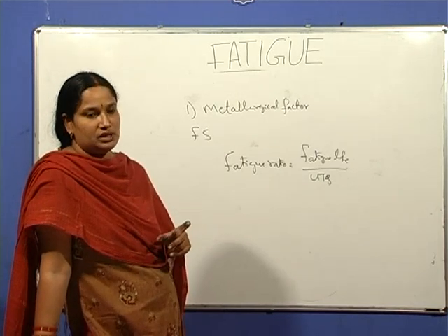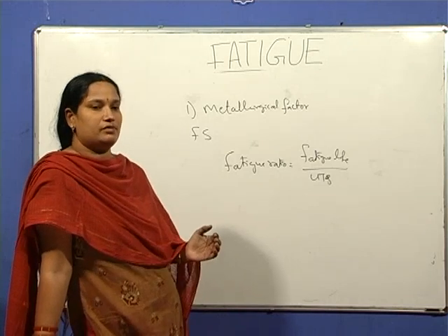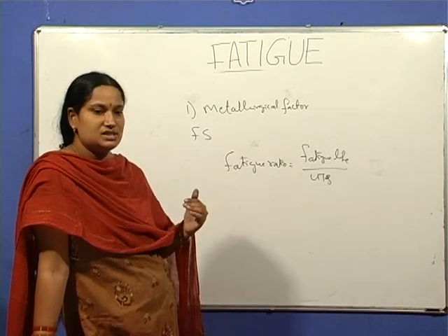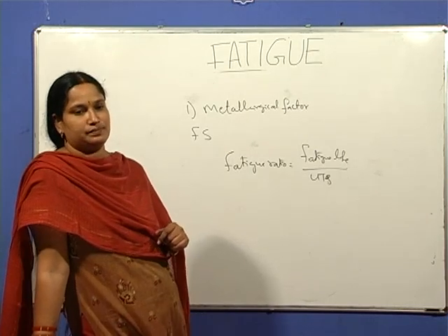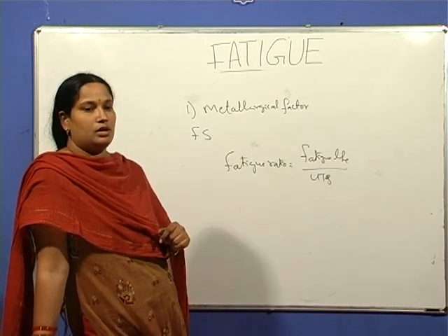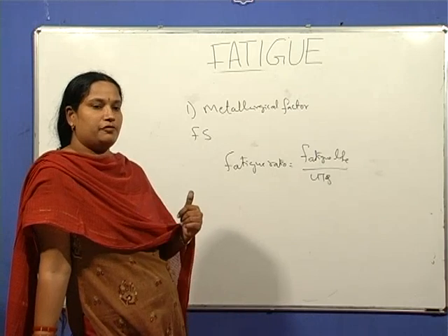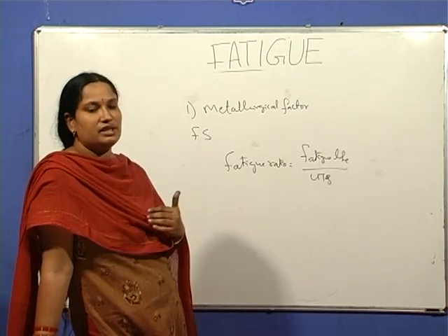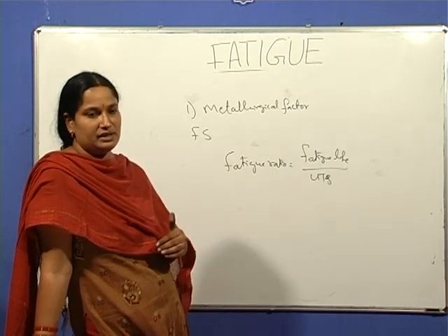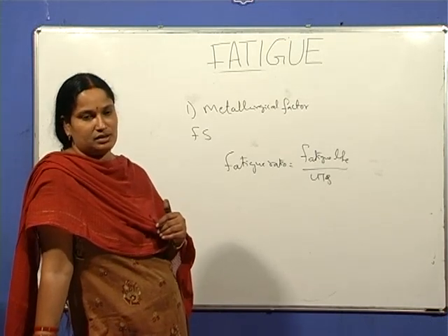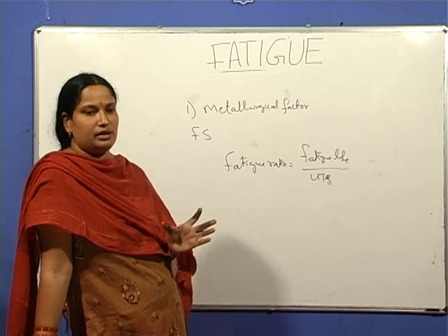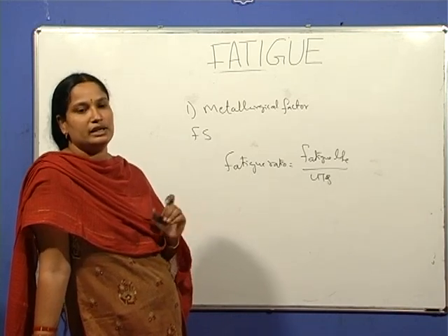Moreover, fatigue properties are more structure sensitive when compared to the tensile properties. For example, if by a strengthening mechanism, such as the precipitation hardening mechanism, the yield strength of the material increases, proportionately fatigue strength does not increase.